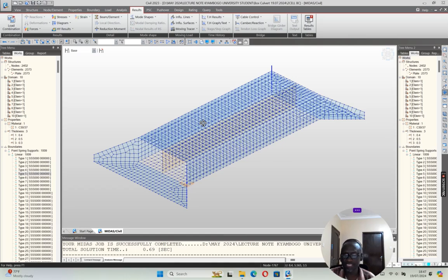So my worst case scenario is when the structure is loaded and there is no water, you have vehicles parked there or traffic moving, such effect is there, then the structure tends to fail. The external walls and the top and bottom slab will tend to curve in, without any counterbalancing pressure from water or anything. So basically that is the situation.